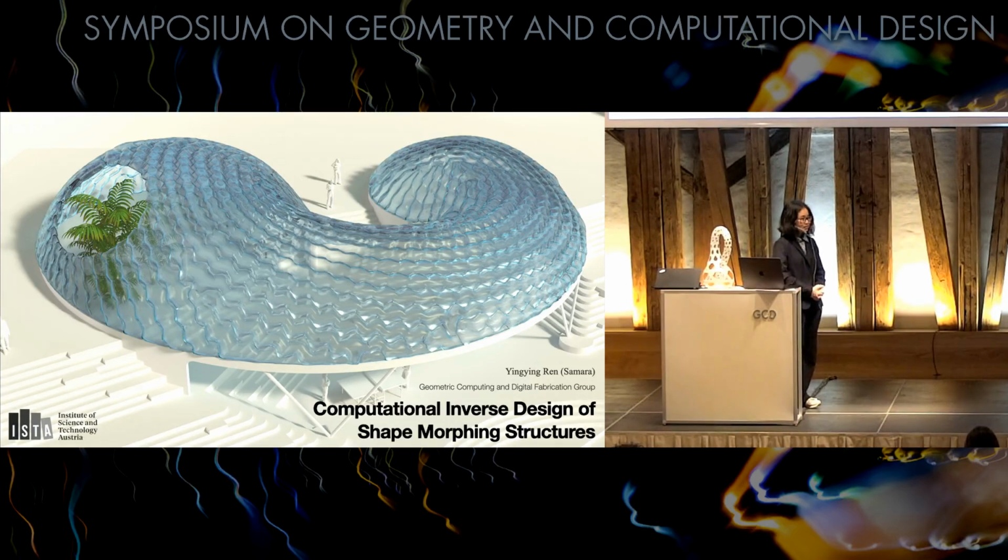Yes, and this is also one of our motivations to analyze these more complex patterns, because in the beginning we have the parallel tube pattern, then when we design with them we get these long individual chambers. But if, say, we use a fusing curve pattern with elliptic holes where the fusing curves are disconnected, which means that the inflation chamber is by design just a single chamber, the air can flow through much more easily. Of course, we still need to do more analysis to find out exactly how these fusing patterns affect air flows, but that's one of the motivations to analyze patterns beyond parallel tubes.